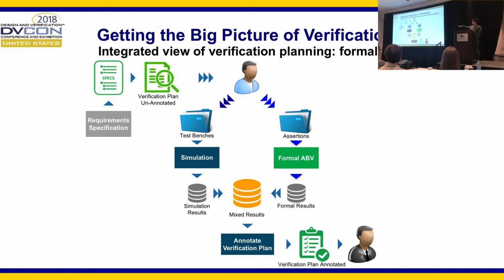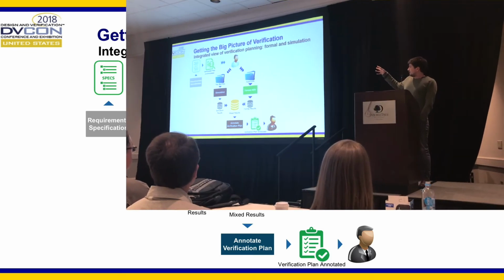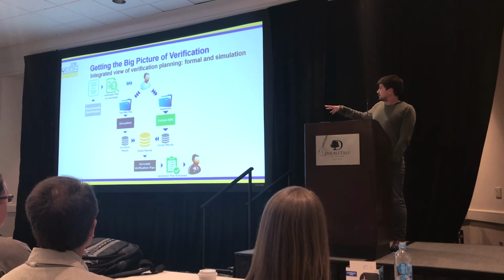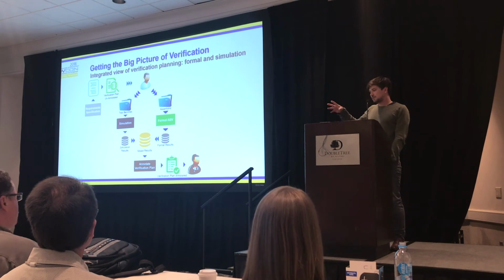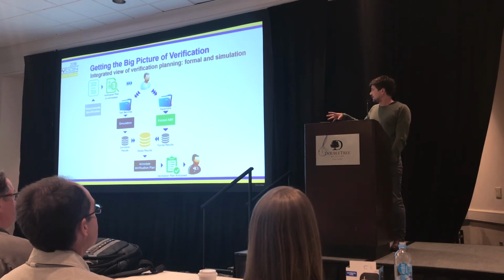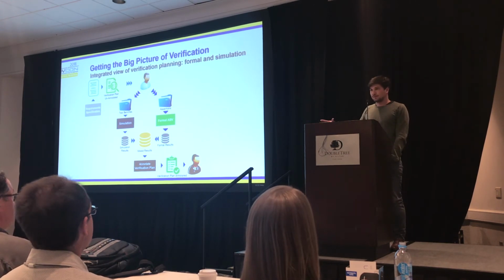As I mentioned before, starting from requirements, everything gets into a spec. From this spec, a verification plan, which is not annotated, is derived. Then the engineer decides whether it goes for simulation or formal, or both. At the end of the day, the simulation results and formal results are merged into a common database, which are fed back into the verification plan, getting annotated, and then are ready for sign-off.